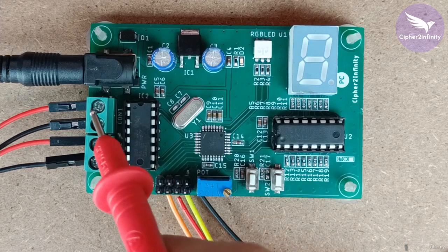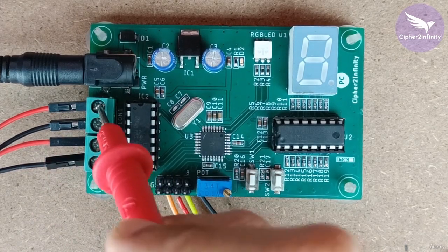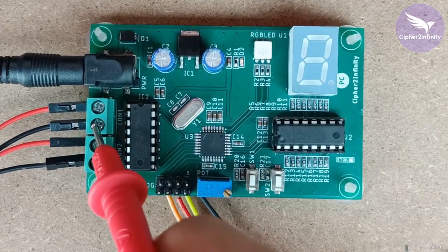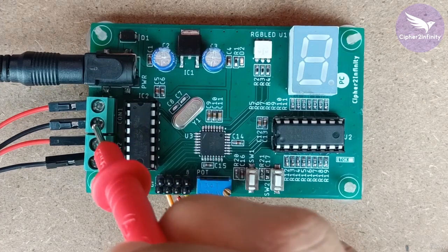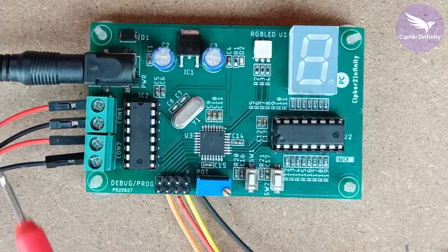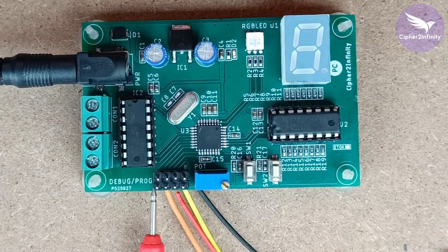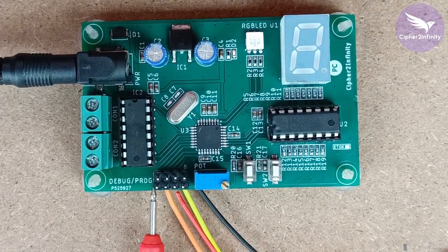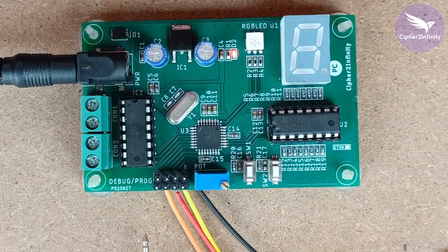Okay, and you can always check the voltage across the terminal blocks. You can verify that if the motor is not rotating, then you can check the voltage across these 2 points. You can connect the positive terminal of the multimeter here and the negative terminal here, and you can check whether you are getting plus 12 volt here or not. Okay, so I will show you that now. So let me just remove all these wires. Alright, so we have disconnected the motors and let me power our system. So the system is now powered, and let me make the space for the multimeter.